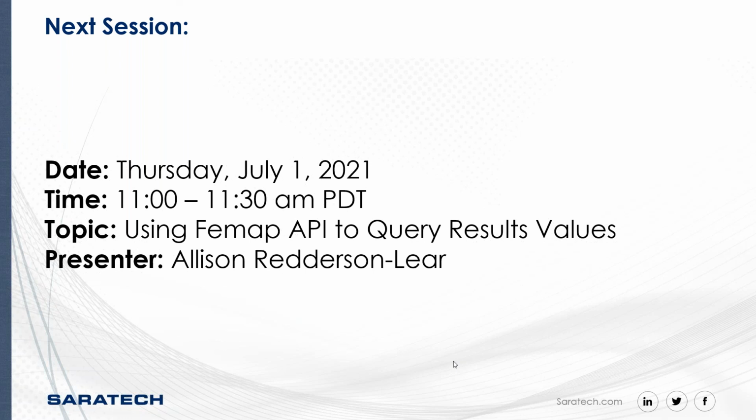The next question is, in rough turn smooth, can we still change our engage and retract settings? Yes, in rough turn smooth, you still have full control. You can actually turn a rough turn smooth into a normal rough operation if you want to. But you still have all your controls in there for engage and retract and non-cutting moves.